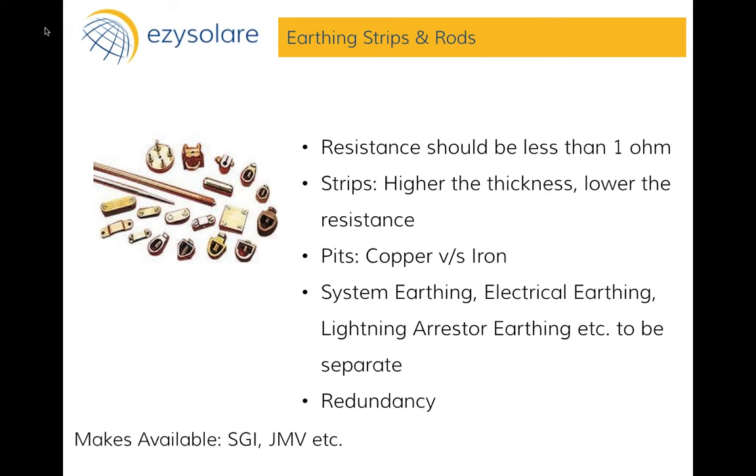The design of the structure, in turn, is first of all impacted by the location of the site, right? If it is in southern India, then the tilt will be slightly lower. If it is in northern India, then the tilt will be slightly higher, which will make changes to the design. The next thing that will be determined upon is what kind of roof are you working on? Is it a shed? Is it an RCC roof? Is it a ground mounted system? Or is it a superstructure that you're building? Different rooftop types will have different kinds of structures.